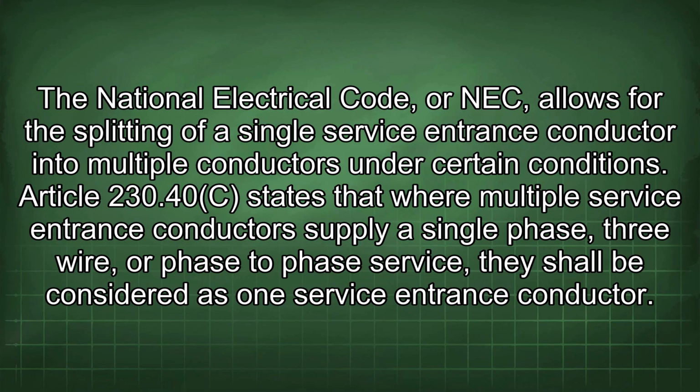The National Electrical Code, or NEC, allows for the splitting of a single service entrance conductor into multiple conductors under certain conditions. Article 230.40(c) states that where multiple service entrance conductors supply a single-phase, three-wire, or phase-to-phase service, they shall be considered as one service entrance conductor.